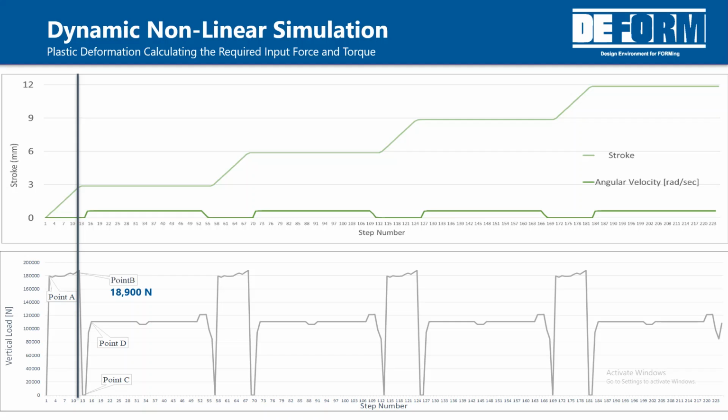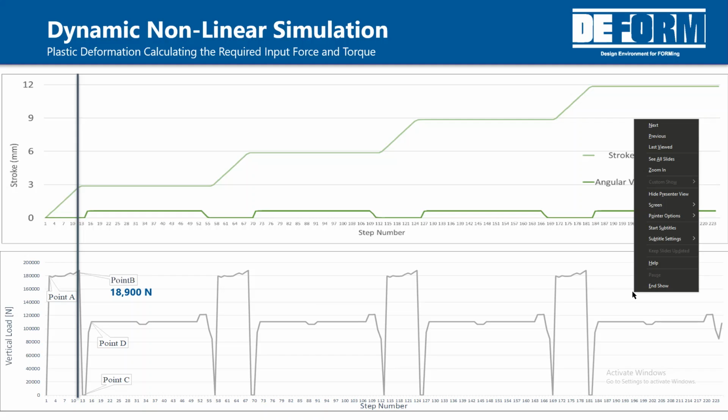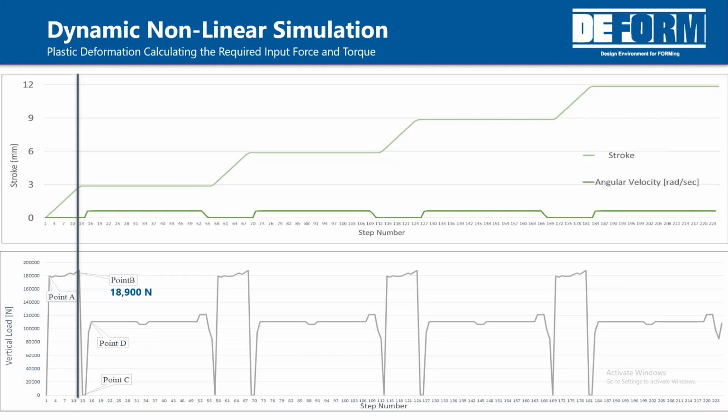The displacement at this point is very small, that is why it is not showing clearly in the animation. After reaching the maximum displacement, the maximum force turns out to be 189 kN, which is equal to around 18.9 tons, reaching point B. A sudden force drop is witnessed at point C in the small period just after the vertical displacement and before initiating the start of the rolling process. It is advised to interpret the result while simultaneously looking at the figure above.